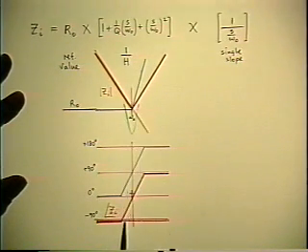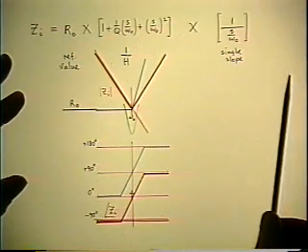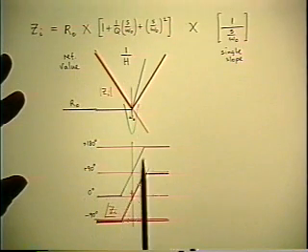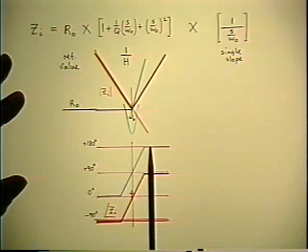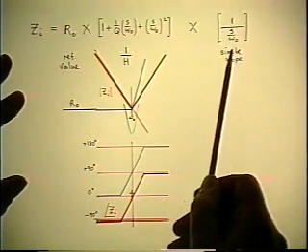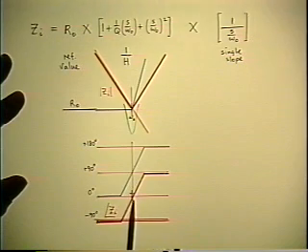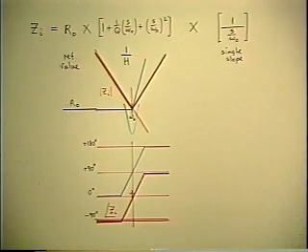You do the same thing with the phase, because I simply add the phase angles from the three terms. The R0 doesn't have any phase angle. The blue line is the phase asymptote for the quadratic in the numerator, which is a phase lead now, 0 to plus 180. And then again a shift because of the constant minus 90 degrees, so the blue line shifts down to the red line. So that's the overall result.